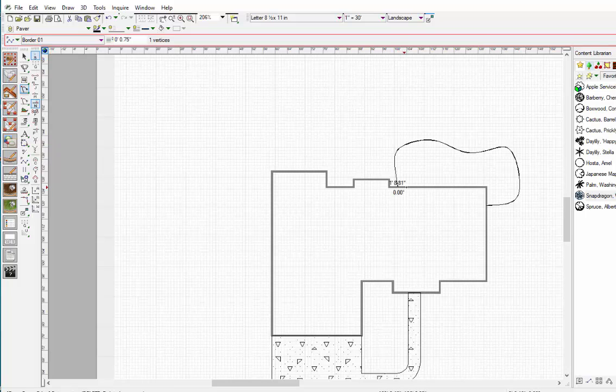Okay, I'll start here, and I'll trace over to the end point. Let's go ahead and hit the E on the keyboard to find the corner, and then I'll find the end of the other edge with a click, and then I'll right click. Okay, so that created two pieces of edging. So I have this piece and then the L-shaped piece here.